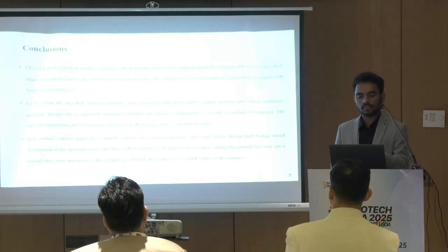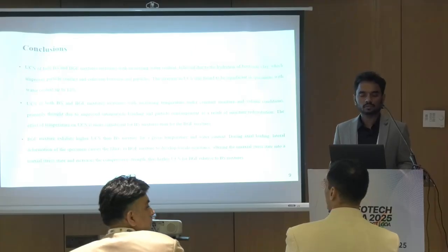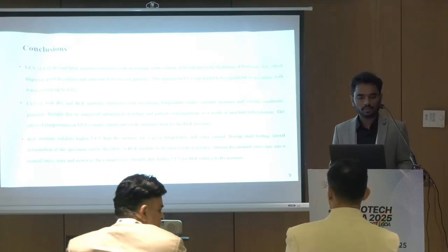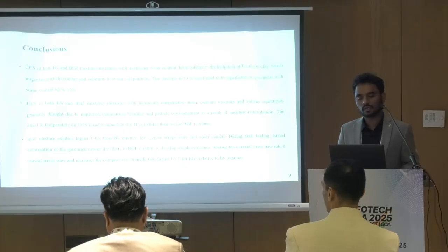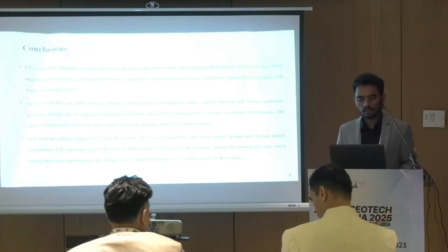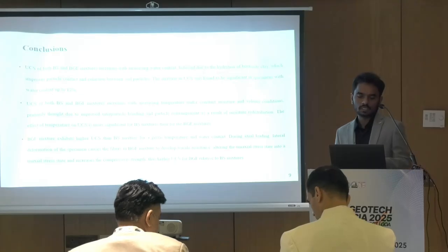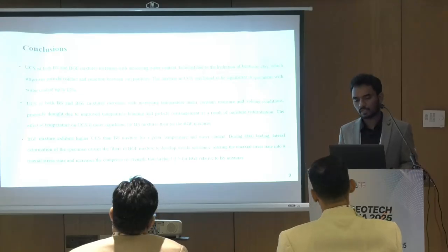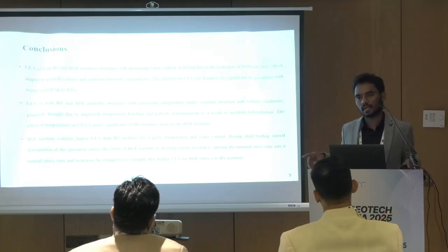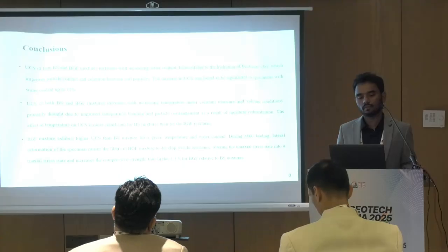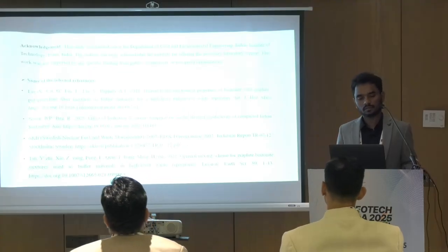The increase in UCS was found to be significant in specimens with water content up to 12%. And the effect of temperature on UCS is more significant for the bentonite sand mixture. In the bentonite fiber mixture, the uniaxial stress is converted to a triaxial condition, so it can take more load, and the fiber is acting as a bridging effect. So it has given much more strength.